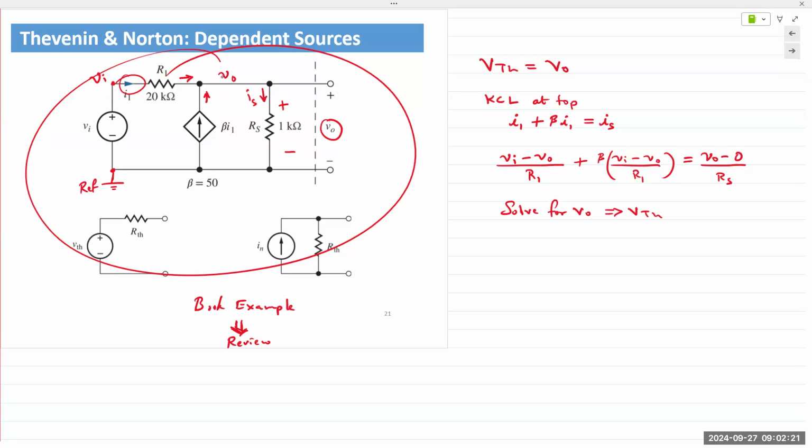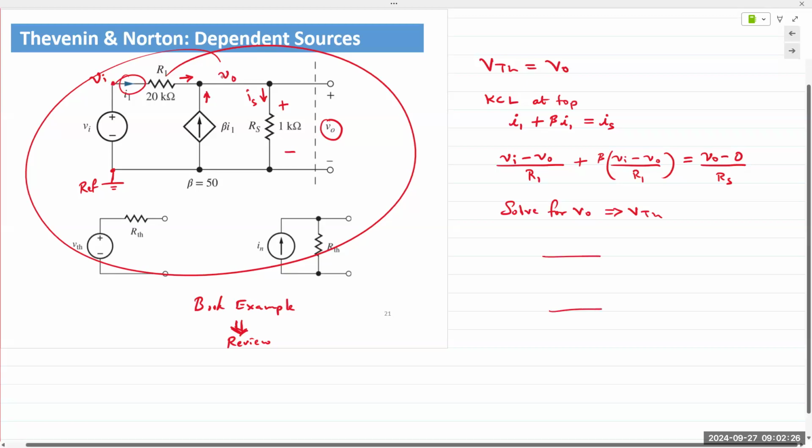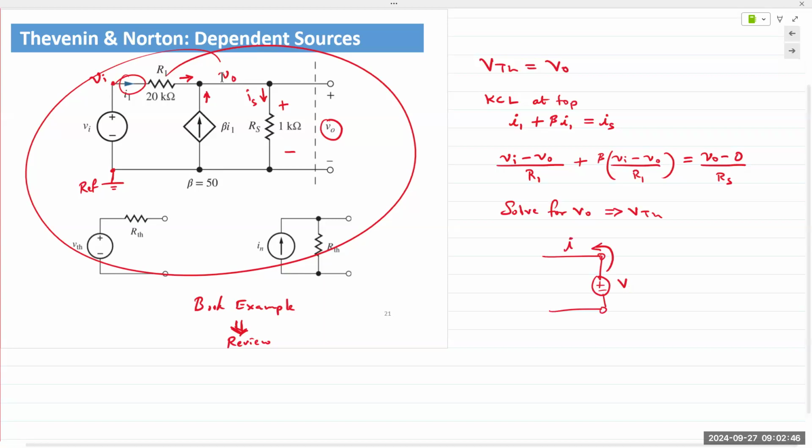The question being asked is about R Thevenin. With a dependent source, at the output we would place a voltage source or some sort of energy source, and then you solve. So you'd have Vx or Vs, and then you'd have current flowing through because of that voltage source. And then your R Thevenin would be this V over I. Any value we wish, it could be any value.